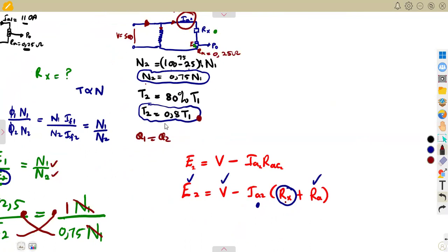There is a relationship that you're given on the torque there. So it also follows that if you considered this condition, remember what I referred to in terms of the E1 that we had. Also, we can consider that T1 over T2 is going to be equal to what? The armature current, because remember, we were considering flux 1, armature current 1, then flux 2, armature current 2.